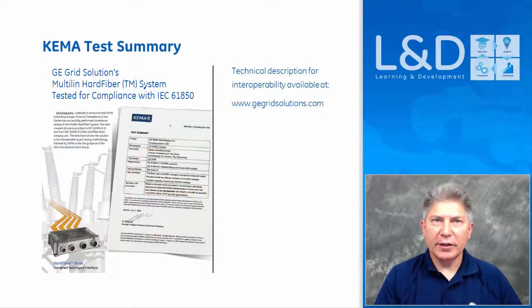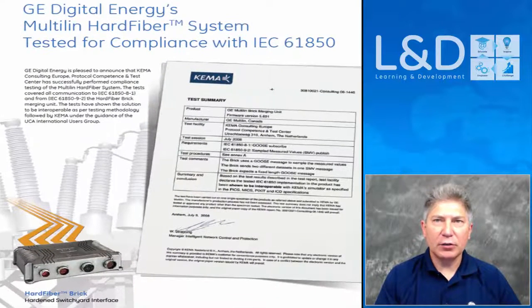The brick HardFiber is IEC 61850 certified as per KEMA. The brick communicates according to the IEC 61850 International Standard Communications Network and Systems in Substations, First Edition. The brick is communicated to via IEC 61850-8-1, and communication is received from the brick via IEC 61850-9.